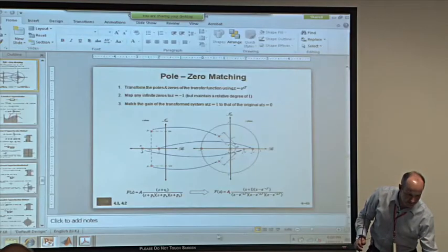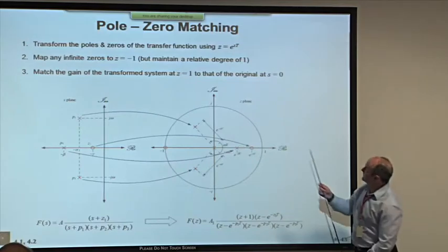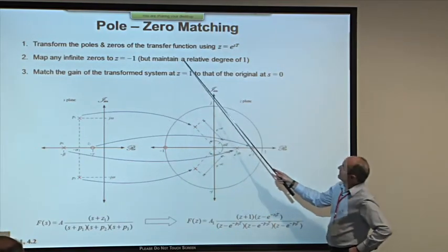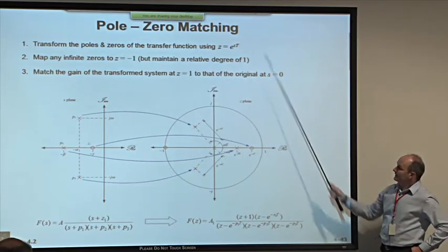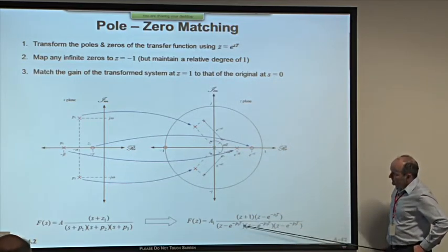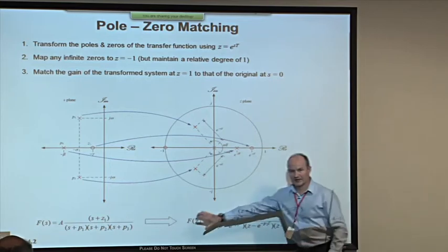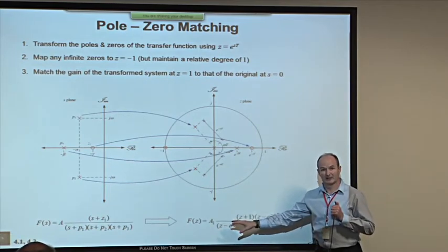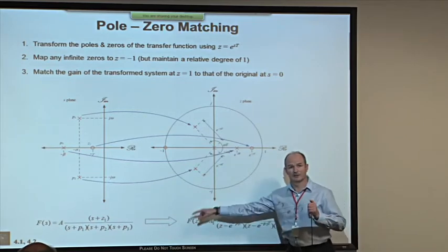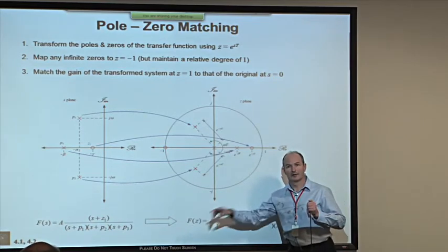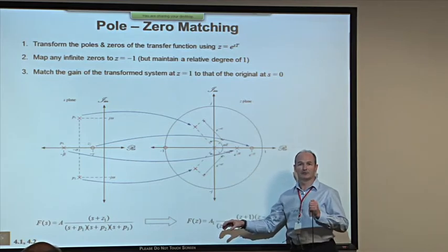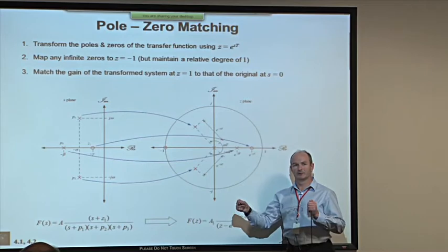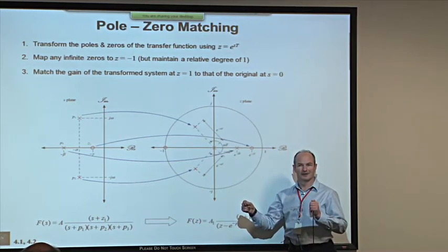Now the significance of step 2 is that when we go back to the 2-pole 2-zero controller, where we've got a relative degree of 1, the form of this, when we construct the difference equation, means that u of k will not involve a term involving e of k. The newest value of input won't be a term in the newest value of output. It'll only be delayed values of inputs that have an influence. So we're waiting one sample period before we compute the output.